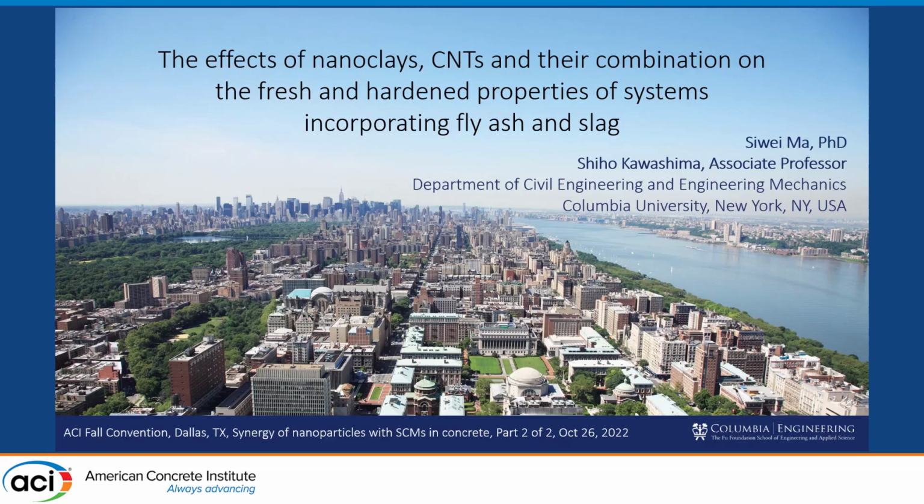I'm going to talk about a performance-based study that looked at the effect of nanoclays, CNTs, and their combination on paste and mortar systems that both incorporated and didn't incorporate SCMs, specifically fly ash and slag.